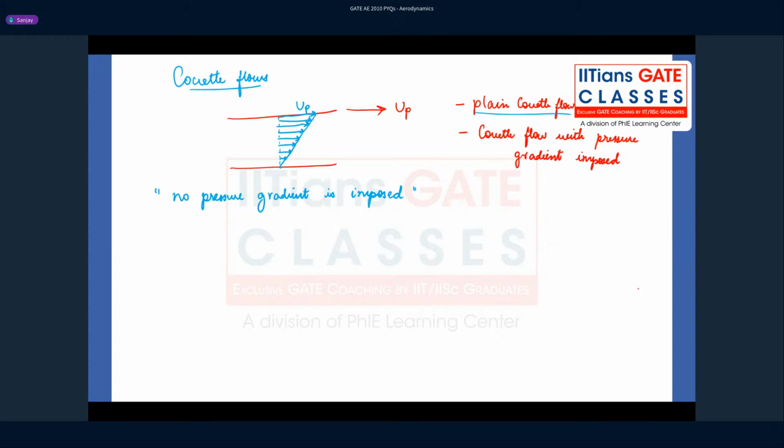So this type of velocity profile, you can guess it from your understanding of the flow physics. But say I don't even know what this Couette flow is, and you are not able to guess it, then how will you arrive at the velocity profile? For that, we have to go back to our Navier-Stokes equation. Let's write down the Navier-Stokes equation for 2D incompressible flow.